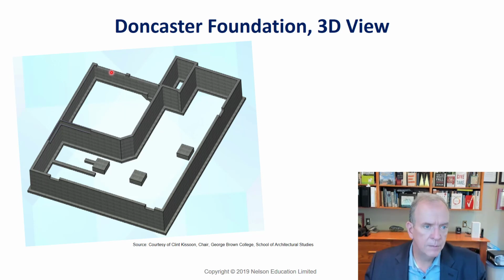And of course, this only needs to be this deep because this will put you 4 feet below the frost line. Here, you're probably like 7'6" below the frost line, but you want a deep basement, right? These are new houses, so you're usually 7'6" to 8 foot deep, and some 9 foot and 10 foot on custom homes.